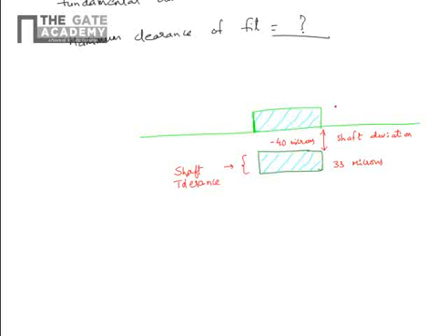So what is the tolerance for the hole? Here we have to remember that he has given IT8, 33 microns. So tolerance for hole, H8, equal to IT8. So he has given 33 microns.